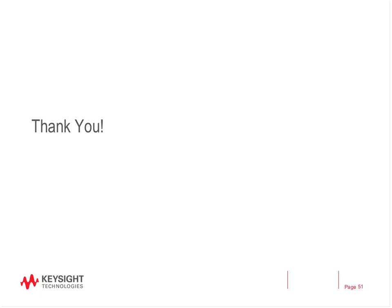That's kind of an internal number that we use. There's a lot of variables that go into K. A lot of them have to do with some of our FFT processing capabilities and capabilities of our ASICs, different levels in there. But usually we don't publish that type of information. But one of them is, like I described earlier in the fast sweep approach, we do basically a correction that applies amplitude and phase correction to the signal as it gets processed through the IF chain in real time. But that's all I can comment today.